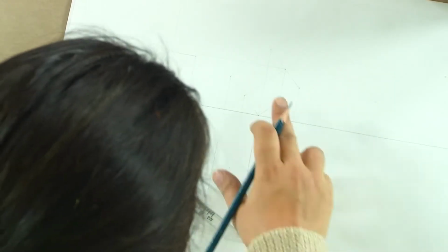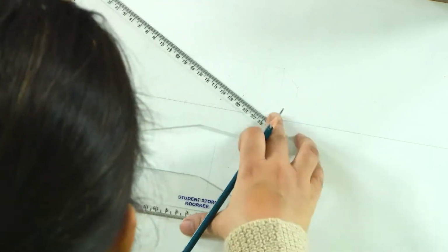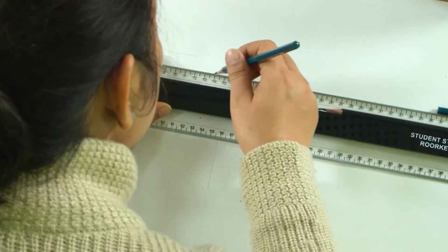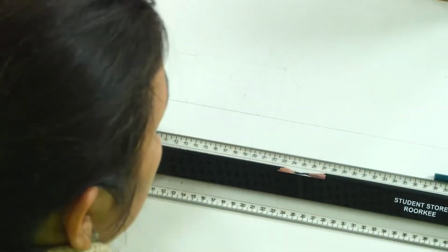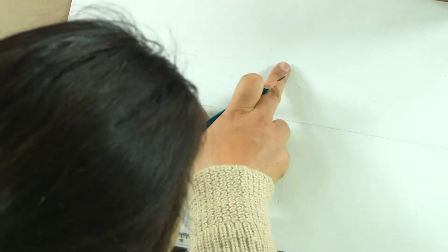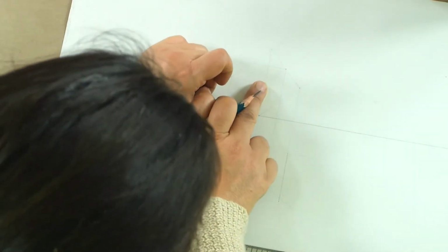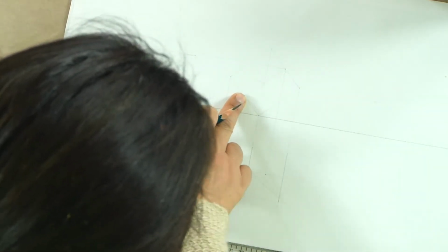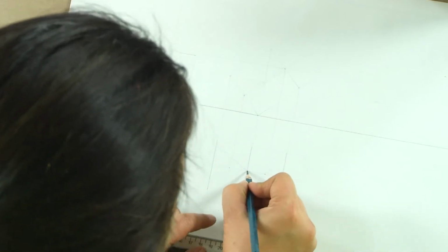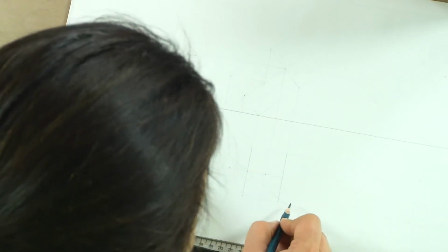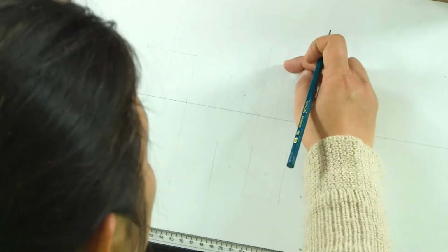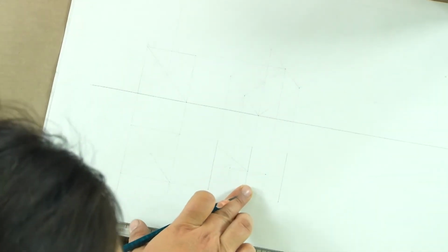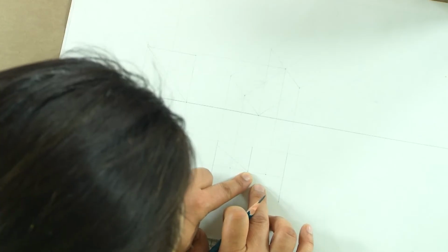Now, if you look at this, this is the midpoint of the axis in elevation. So this is our reference line. Half of the axis is inclined about this point, or probably this entire axis is inclined about this. Further, when we incline it, this is going to be the point, and this is the 30-degree line. Now the trace of this is going to be inclined at this 30 degrees.